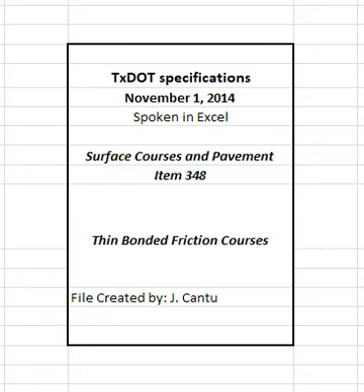The engineer may allow mixture placement to begin before the roadway surface reaches the required temperature if conditions are such that the roadway surface will reach the required temperature within 2 HR of beginning placement operations. Place mixtures only when weather conditions and moisture conditions of the roadway surface are suitable as determined by the engineer. The engineer may restrict the contractor from paving if the ambient temperature is likely to drop below 32 degrees Fahrenheit within 12 HR of paving.